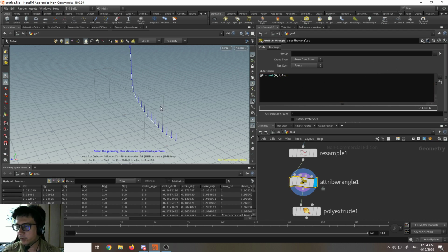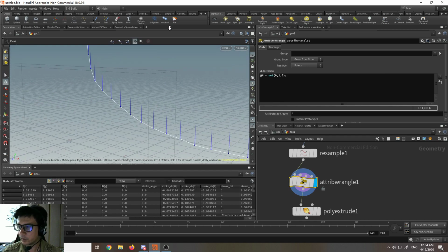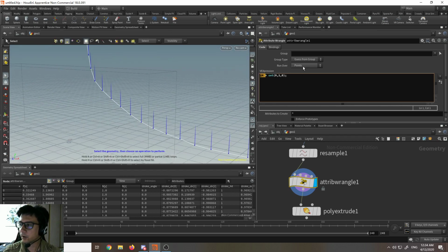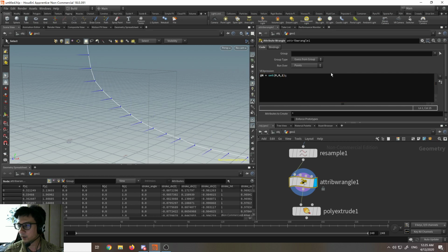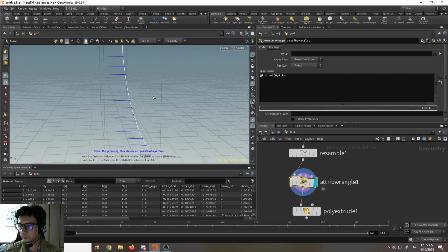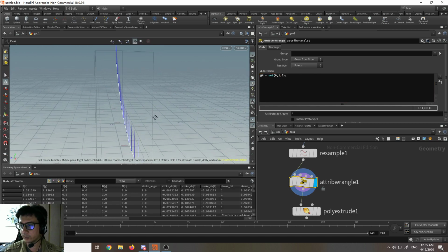And you can already see what this does. Basically, it's the normals on the points, which these are my points, normal primitive, set them to 0 on x, 1 on y, and 0 on z. If I change this to 0, 0, 1, they will run over the z axis. Right. So really, it's not hard to code this.